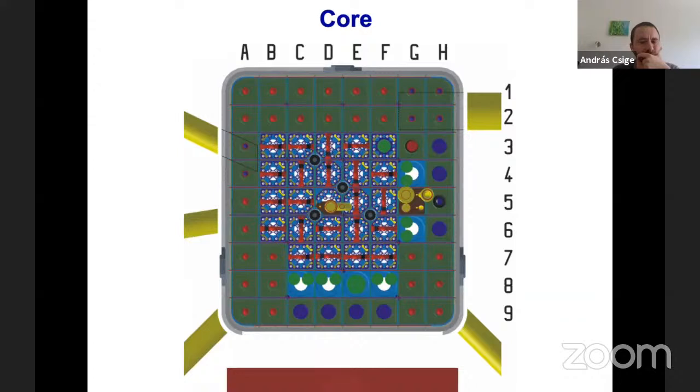Safety limits for reactor power are set by the operator. Different limits are needed for different experiments. Rate of change limits are hardwired. If power is increasing too quickly, then we have a scram.